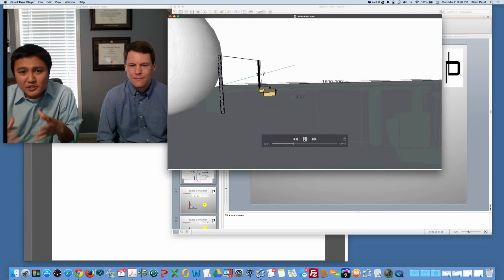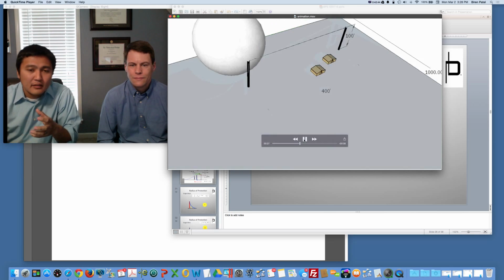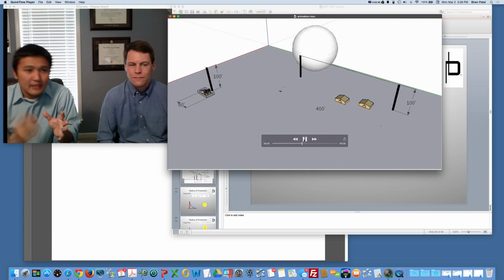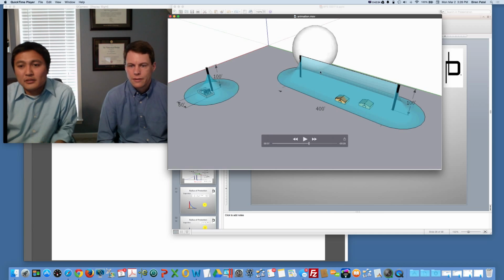We're going to roll the sphere, and every time we hit a shielding electrode, whether a mast or a wire, we stop the sphere and go around it. And it's going to create some zones of protection. You can kind of picture the zones of protection already, but here we go. In 3D, you can see this shape, which I like to call a tent shape. You've created this tent-shaped zone of protection.